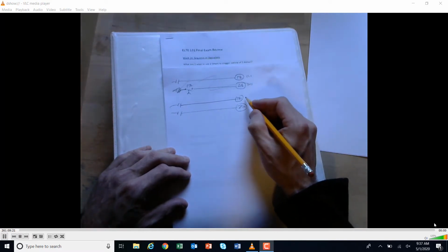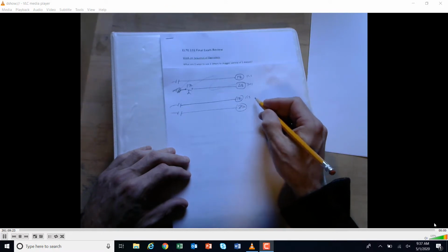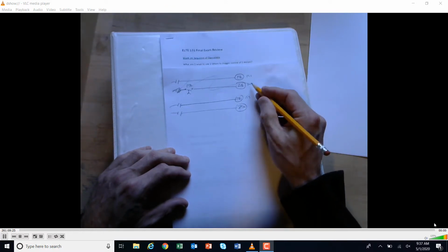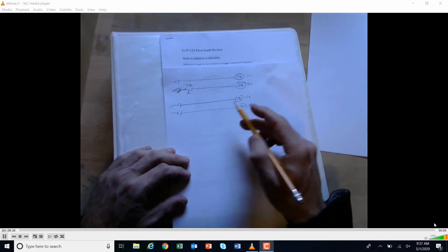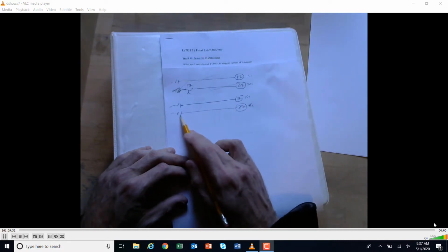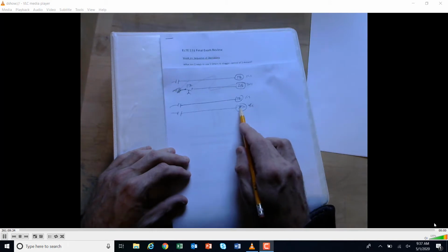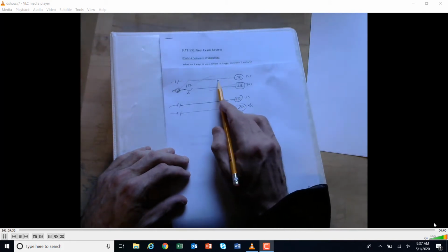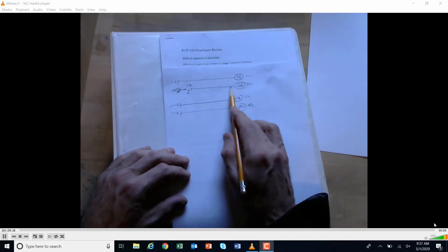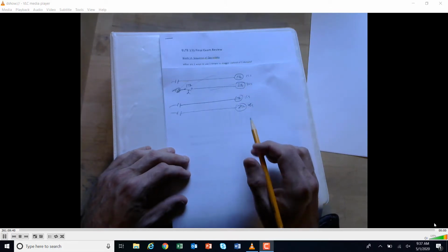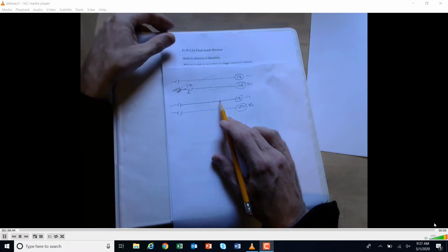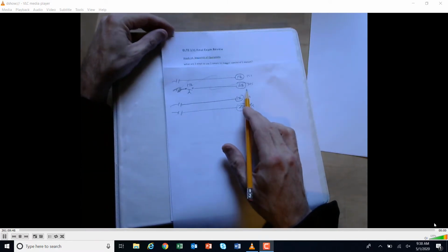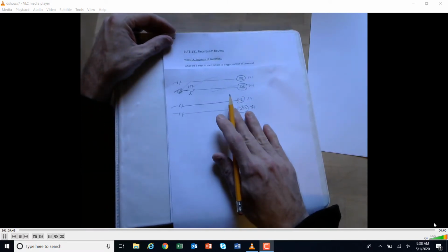and they would turn on both timers at the same time. And in this case, this one would be for 15 seconds, and then this would be the addition of the 2, which would be 45 seconds. So something could occur after 15 seconds, and then something could occur after 45 seconds. So these are kind of in parallel. These are kind of in series because one starts another, cascading. Okay, and then knowing how all the contacts work to start the motor or control your devices, that was what we learned about.